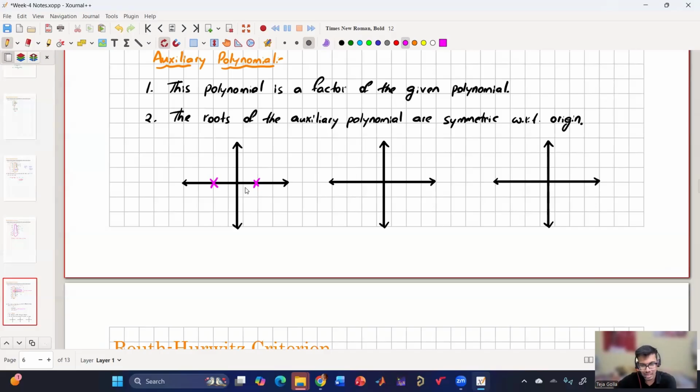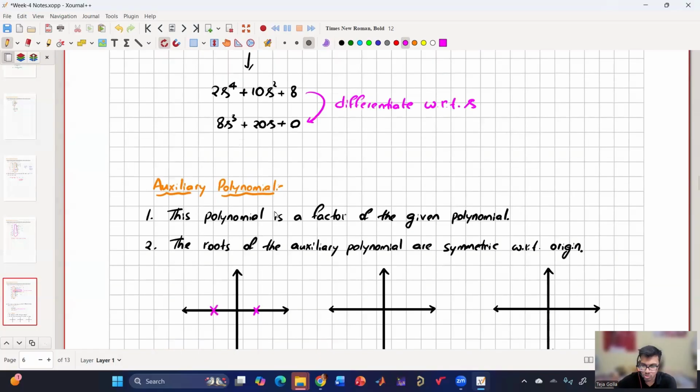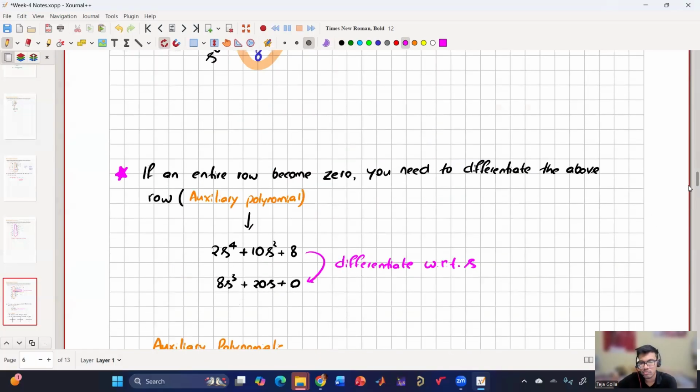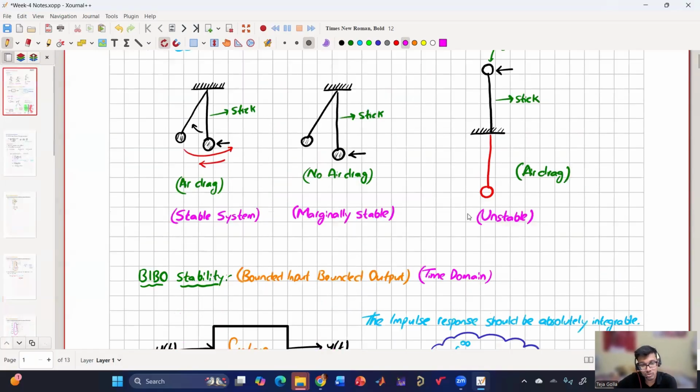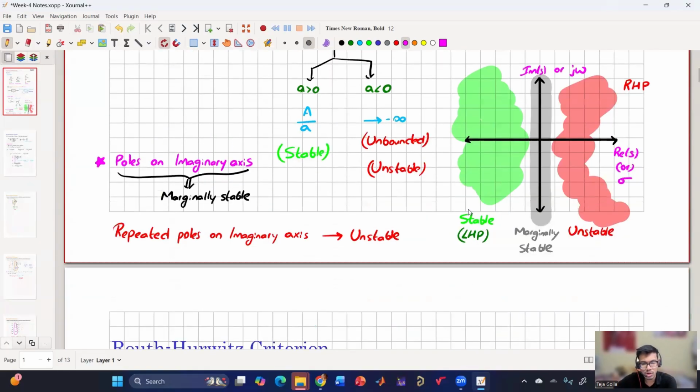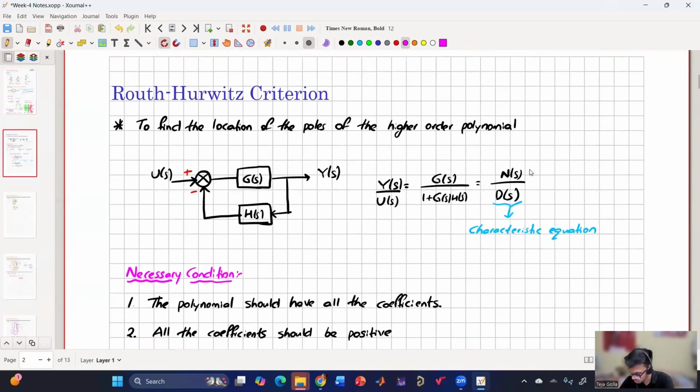So in this S plane, basically, we will be plotting the poles as well as the zeros. So when I use any terminology, I have to define. The roots of the numerator are called zeros, and the roots of the denominator are called poles. And usually zeros are denoted by O on the S plane, and poles are denoted by cross on the S plane, and it is universal.